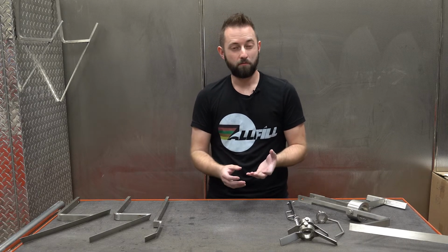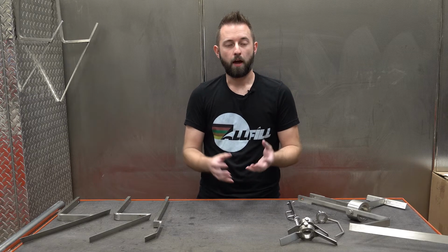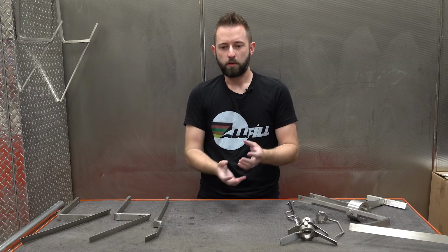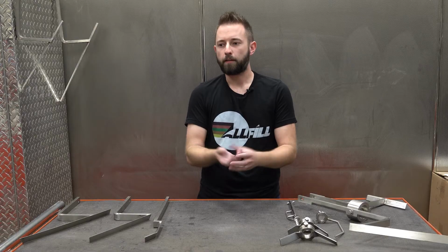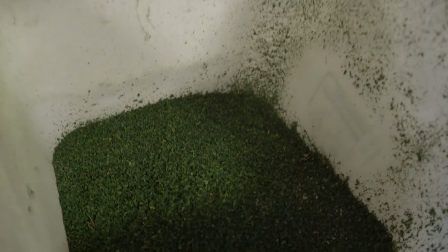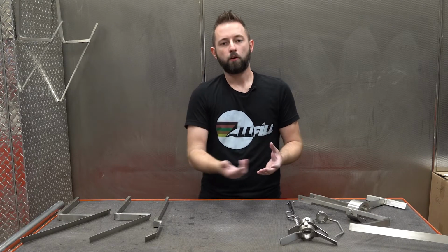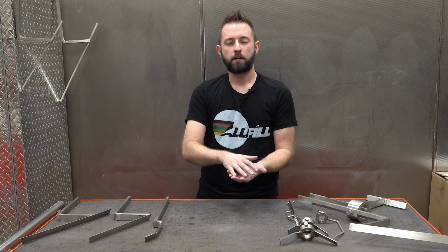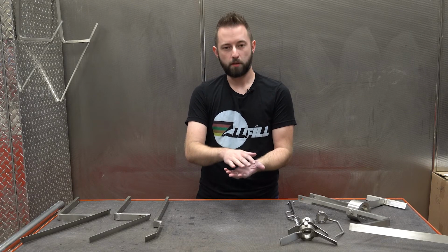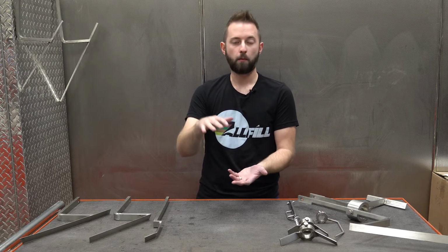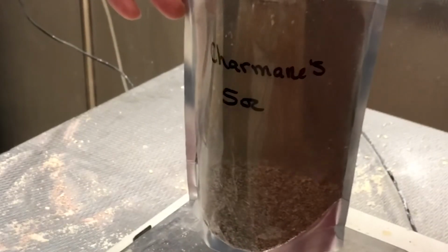We can also use that for products that have, for instance, a spice blend, where you can have separation between, let's say, a spice blend that has paprika and a parsley flake or thyme, some sort of a leafy product in it as well. What you'll notice over time with regular agitation is you can actually start to see the lighter, lower density product, the flake, separate out of your mixture, and it'll be a nice layer on top of the hopper. Obviously you don't want that because it's a spice blend.